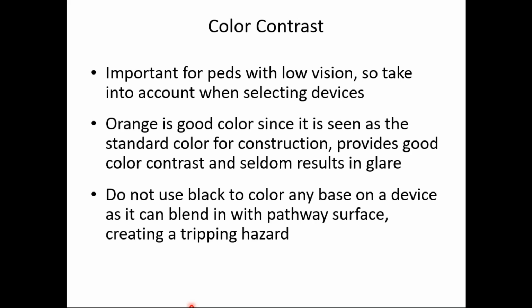Also, one other thing to keep in mind, I would avoid using black to color any base on a device. And I'll show you an example here towards the end of the session. But that black can blend in with the pathway surface, and especially at night or dusk or dawn, in low light conditions, can create a tripping hazard, not only for the disabled, but also for able-bodied pedestrians. So again, there's no prohibition in the manual or in PROWAG, but I think experience shows it's probably best to avoid the use of black to color any base.